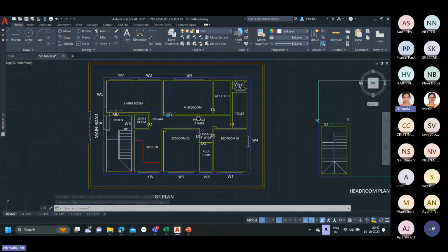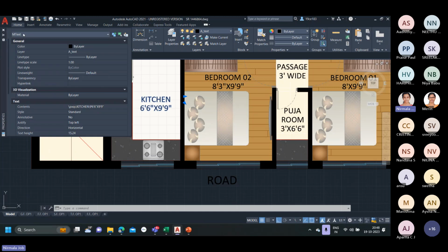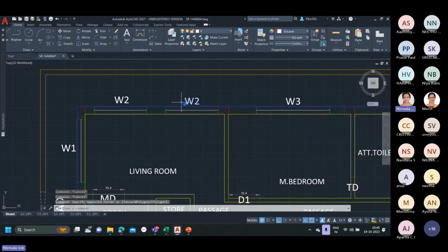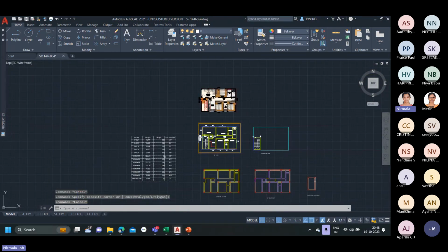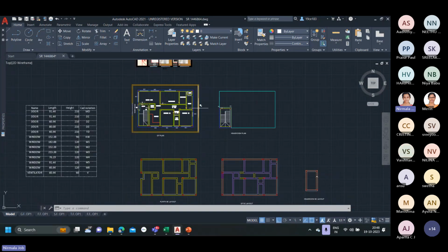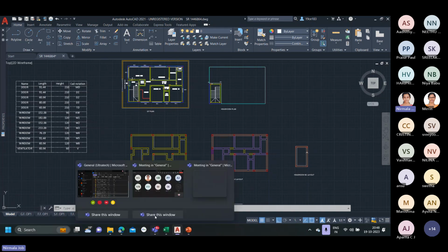That is, if I show it in this figure, I can see that in the drawing provided by the client, the text is done using mtext command. And for our drawing, all of these texts should be in single text command, and hence it is shown over here in the format as text. So like that, we have completed the joinery table, the layer assigning method, and drawing the structural components of each and every architectural floor. So that's all for today's session.